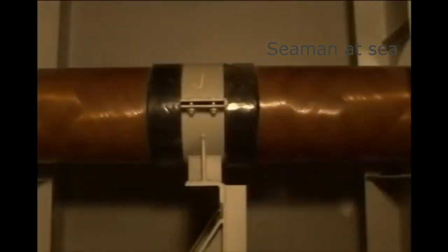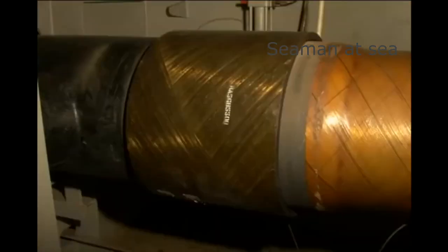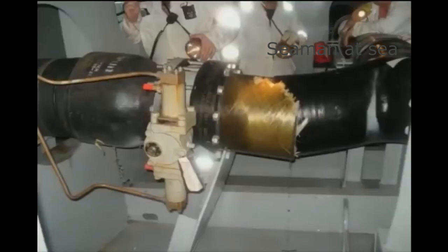Shown here is a pipeline laid on the ship's bottom, through which seawater flows for ballast filling or discharging. Joints that connect the pipes are called dressers. There are cases where dressers are damaged. This is an example of a water leakage accident due to dresser breakage, caused by abrupt valve operation.